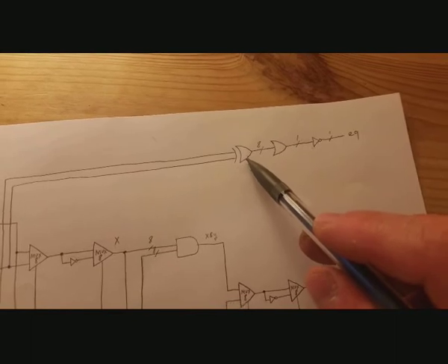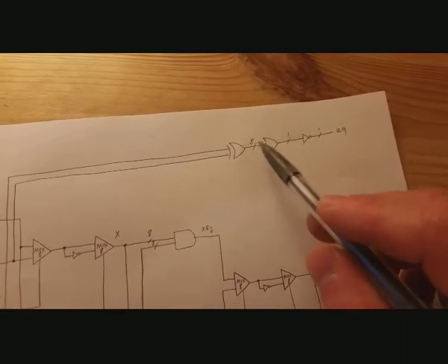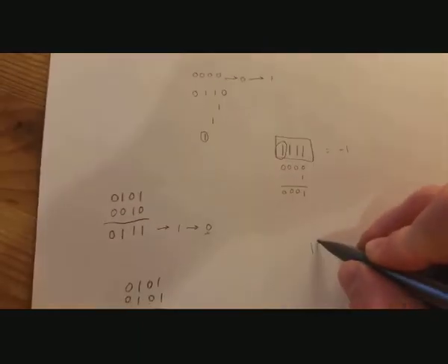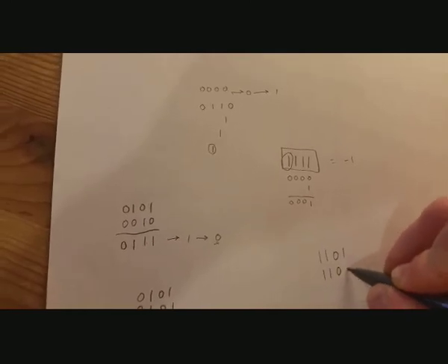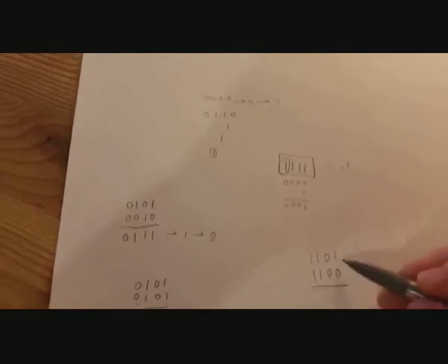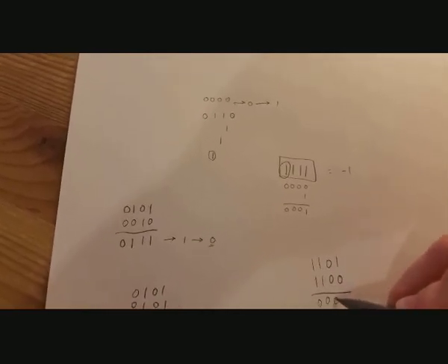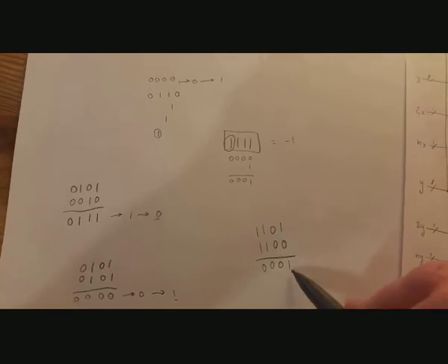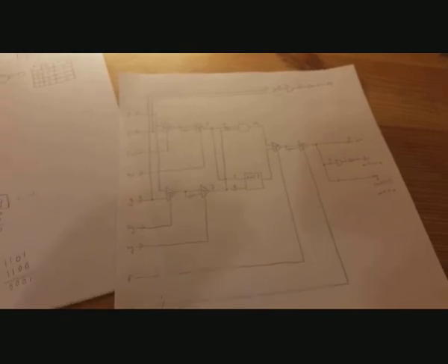We're going to XOR each one, and if you had numbers where they were all the same except one bit, you would get 0 0 0 in the XOR, and then a 1. So if you have even just one bit where they're different, you're going to get a 1 in the XOR, and then you're going to OR all those, and that 1 is going to persist through, and you're going to get a false for equality. So that's a quick overview of the circuit.